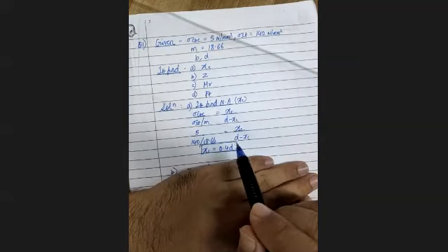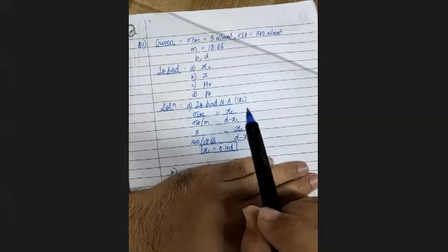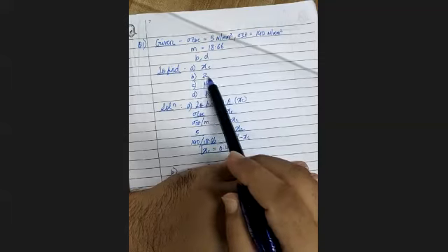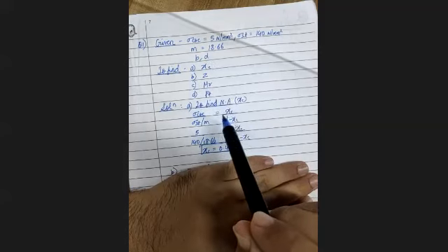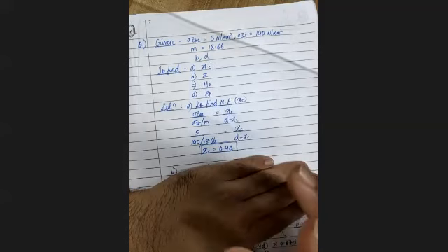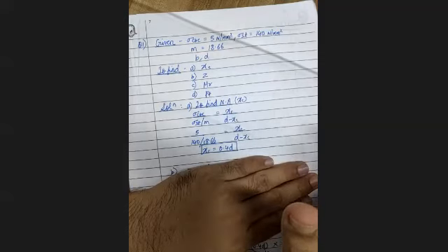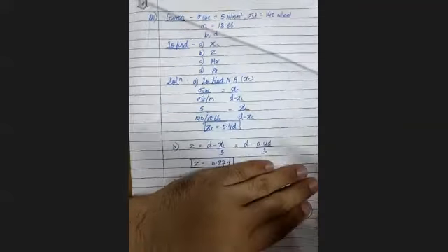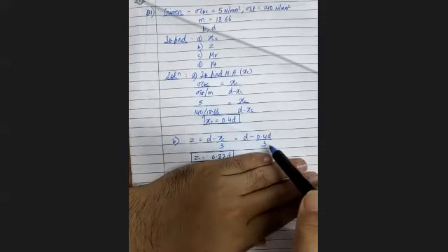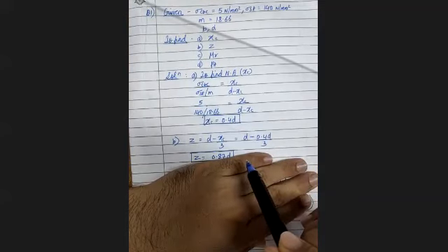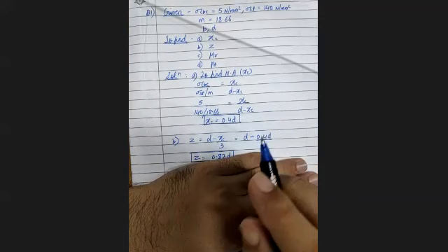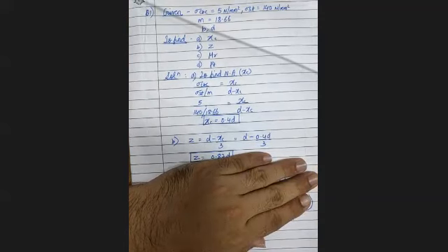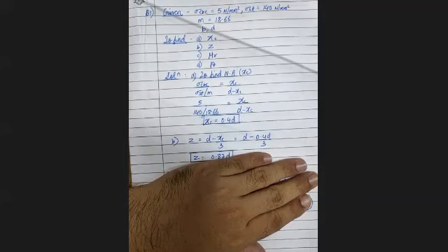Is that clear, everyone? Now let us go for the second unknown, that is lever arm. So what is the equation of lever arm? Z is given by D minus XC by 3. Am I correct? So let us see. D minus XC by 3. XC is nothing but in terms of D. Now what is the value of Z? Anyone? Write in the chat box. I hope the others are getting the value. 0.867 D. 0.87 D. Correct, correct.